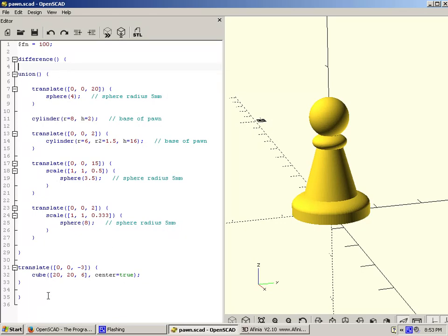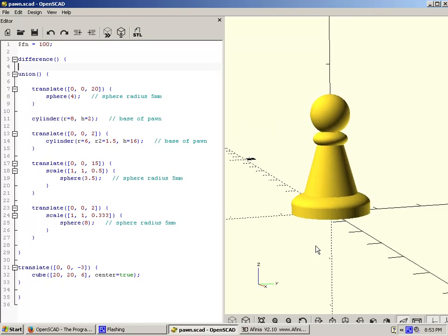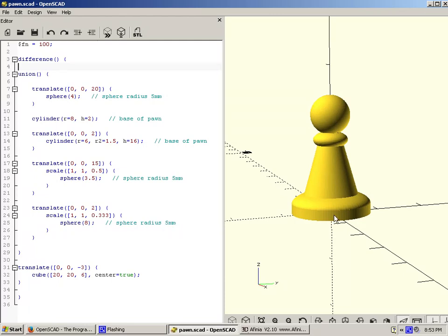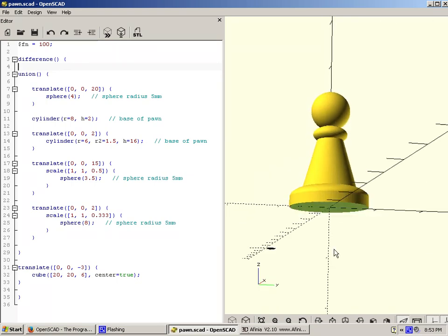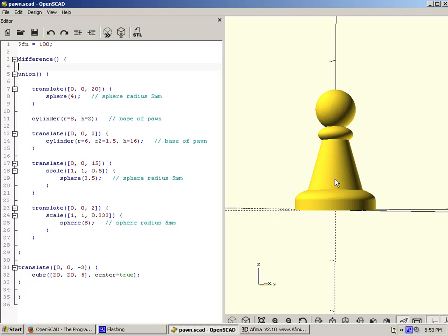So that's just a quick look at OpenSCAD. We may get into other more complex examples, but this is just a good starting point, adding various primitive shapes. So we covered our sphere, our cylinder, our cylinders creating cones, as well as scaling primitives. We also looked at the cube there for the purpose of subtracting the overlapping bottom portion of that scaled down sphere, as well as the difference function and the union function.